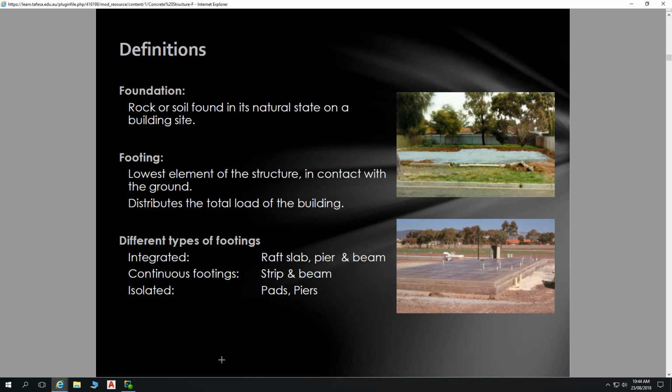And those foundations can then be improved by bringing in compacted rubble, etc., compacting that, producing a better foundation. But then the footing, that's the lowest element of the structure. So in that case, a raft slab.